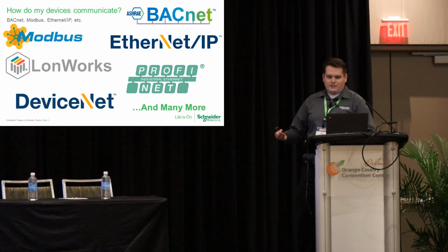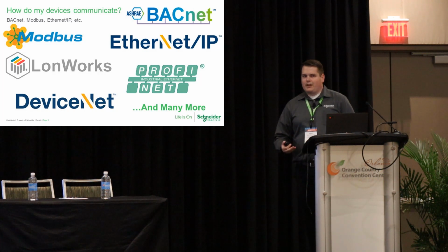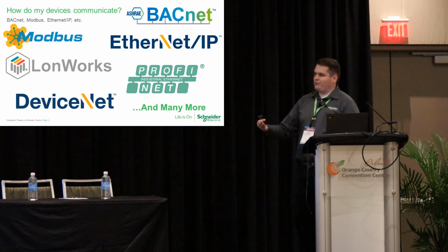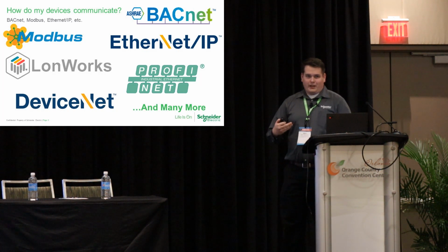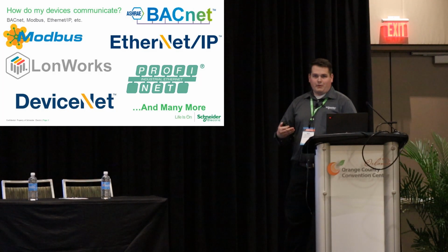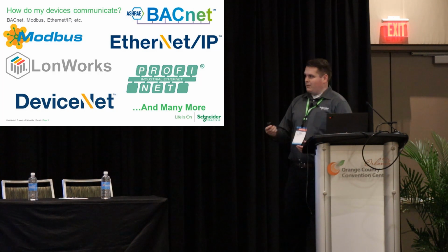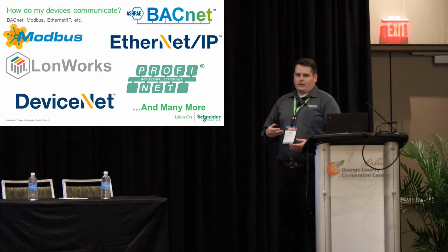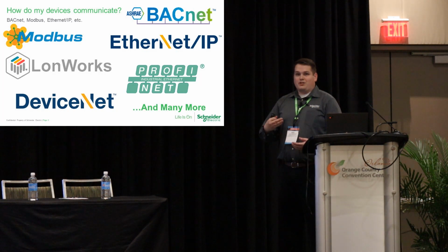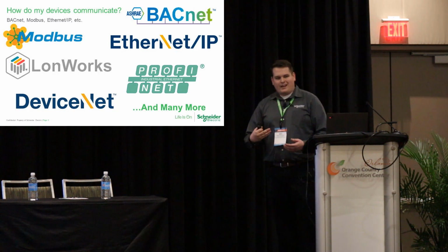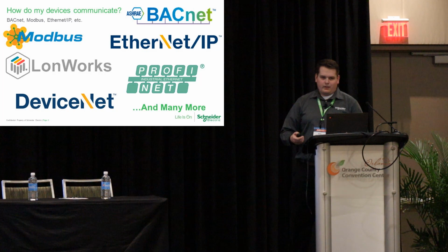More or less, most of your devices you see in the field will have some sort of Modbus communication, whether that's at the base level or going out to a field device. All of ours communicate amongst itself over Modbus, and then we've got other add-on protocols after that, whether it's BACnet, Ethernet IP, PROFINET, PROFIBUS. All of those can be added on in addition to Modbus. Personally, we always have Modbus in our devices, though.